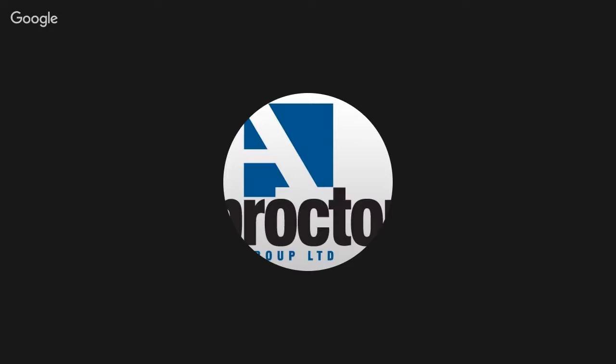Jumping to a quick one about software, are you finding much difference in results when using WUFI modelling instead of Glaser? Yeah, the Glaser method has been very successful for many years, and the Proctor Group have been able to provide condensation controlling calculations for a number of years using the Glaser method. However, it does have limitations. It's steady state, only looks at moisture movement in one direction, and doesn't take into consideration driven rain, or indeed absorption or porosity.